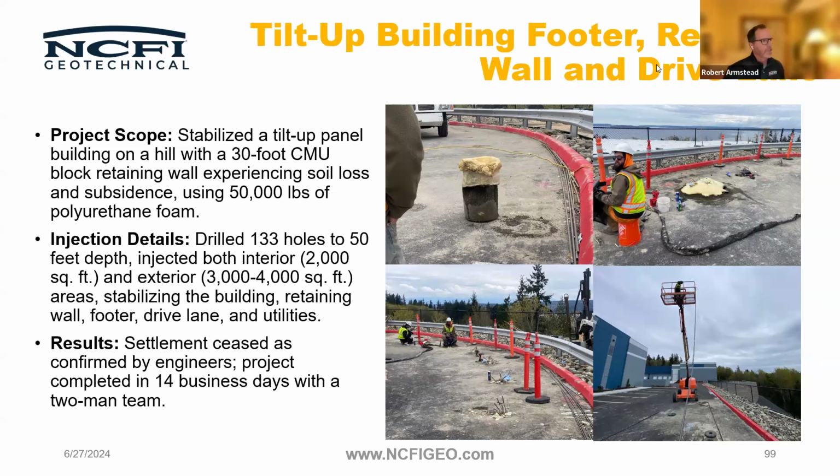How do you check soil density or void size to figure out how much foam is needed to stabilize? The DCP or a geotechnical report will give you some of that information. There are people working on ways to quantify the space between particles of soil, I can't think of the word right now.